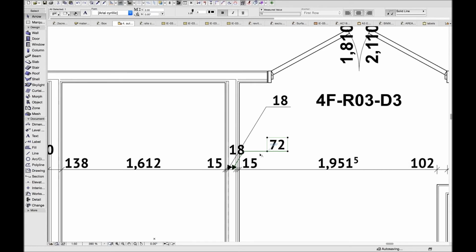With these new leader lines, the dimension text can have multiple rows now. Many architects are required to add the minimum or maximum values or other extra prefixes to the dimensions. Now with this function, if I go to the custom text, I can add the minimum prefix, and I can type the break line symbol. So now I can have multiple break lines in my leader lines.